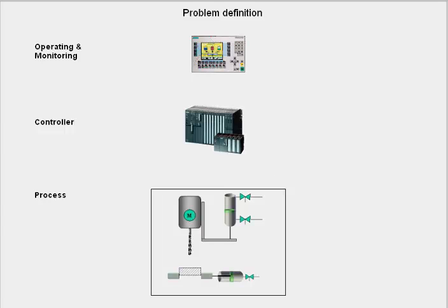Let us take a fictitious fault in the system. A standard alarm system informs the operator of a symptomatic fault by a display on the HMI device. Now, to determine the cause of the fault, for example, which missing step enabling conditions are holding up the process, you need a programming specialist who has to analyze the user software with a programming device. This sort of procedure usually results in long standstill times.